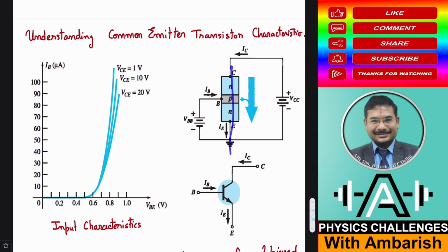Most of the electrons will go into the collector, and that's why it is shown that the base current is very, very small and the collector current is almost the same as the emitter current. So actually the electron flow is like this, and this arrow is for the conventional current. So conventional current is in the downward direction, against the flow of electrons. So this plus this join together to form the emitter current. That's simply the junction law. Base current and collector current together should be equal to the emitter current.